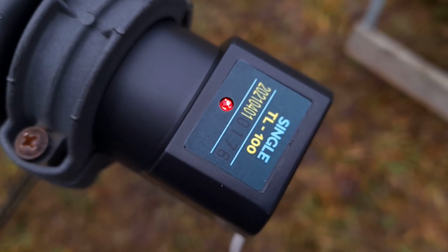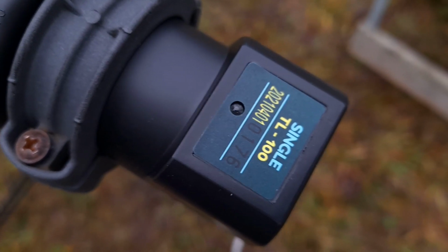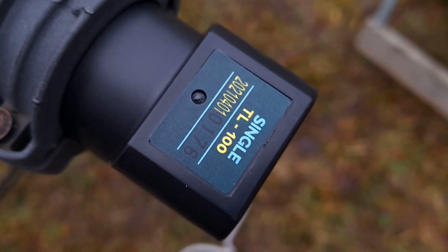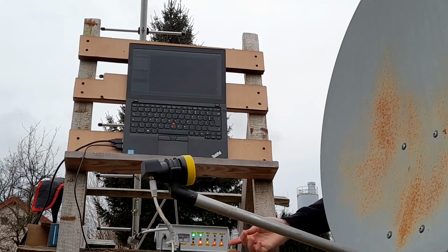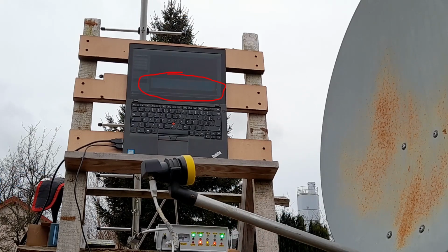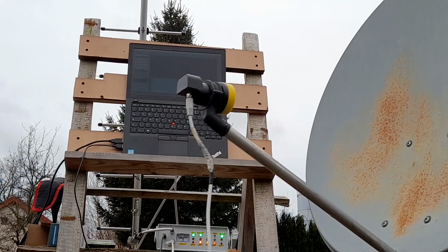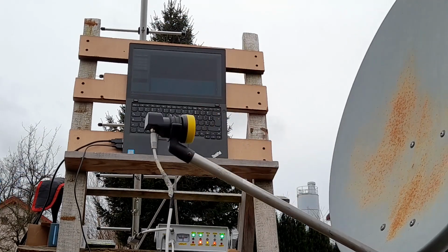When the LNB is powered up, which is conveniently indicated by the LED this one has, you should see a significant increase in the noise floor level in your SDR software. If that is not the case, make sure your gain isn't set too low, although the IF amplifier of an LNB would usually power through even a 0 dB gain on the SDR.